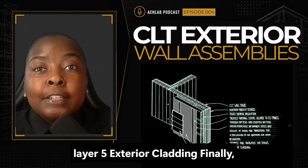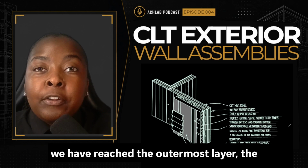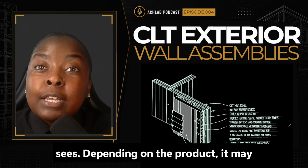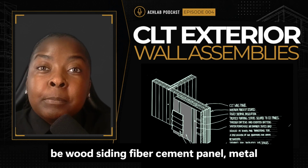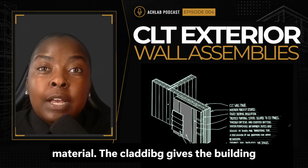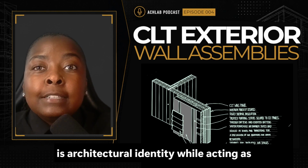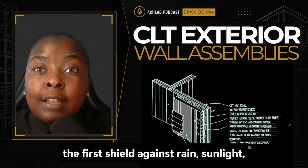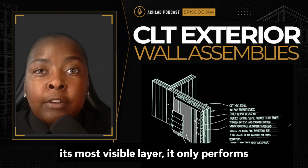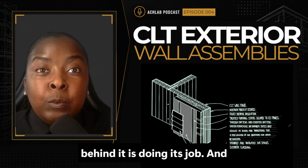And layer 5, exterior cladding. Finally, we have reached the outermost layer, the cladding. This is what everyone actually sees. Depending on the project, it may be wood siding, fiber cement panel, metal panel, brick veneer, or composite material. The cladding gives the building its architectural identity while acting as the first shield against rain, sunlight, wind, and daily weather exposure. Although it's the most visible layer, it only performs well because every other hidden layer behind it is doing its job.